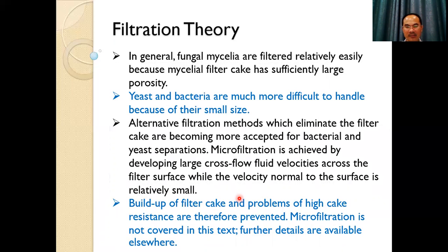Moreover, if the particle size is very small, we have to treat the mixture before filtering. We can use the precipitation technique or the solidification technique. With these two techniques, we can increase the size of the particle before separation. If the size is very large, it is heavy, and then we can separate by gravitation.